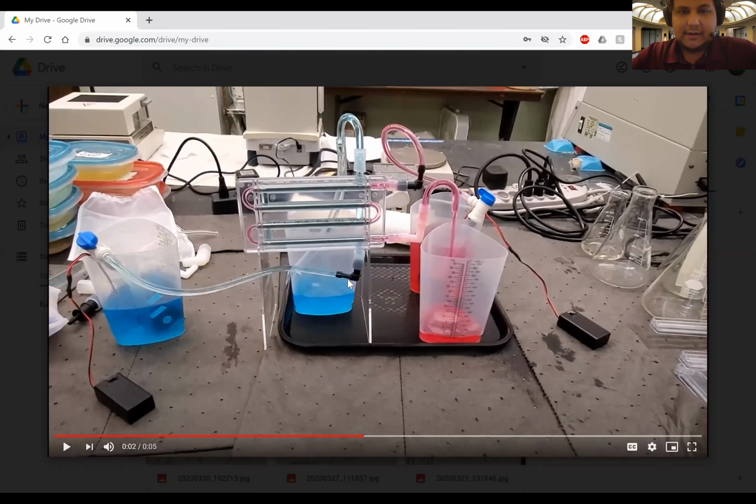However, there are sections where the cold fluid's moving up as well as the hot fluid's moving down, outside and away from those fluids. And so we don't have perfect contact, and we don't have essentially perfect countercurrent flow. And the way we can correct for that is by use of our F factor.